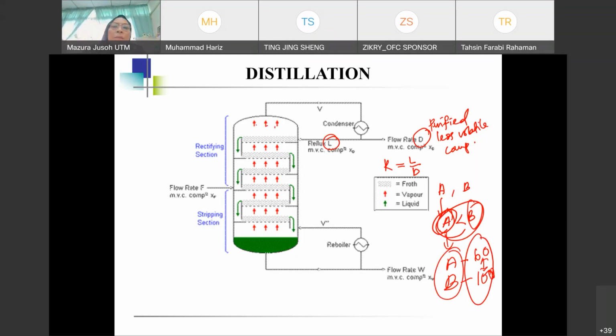All right, so once you've got enough condensed vapor, what's going out here is called V, which is vapor. Once you have enough condensed vapor with a full or partial condenser, you will be returning a ratio of the flow rate to go back into the column as reflux. So when you have the reflux going into the column, only then will you have a collection of liquid on the first plate.